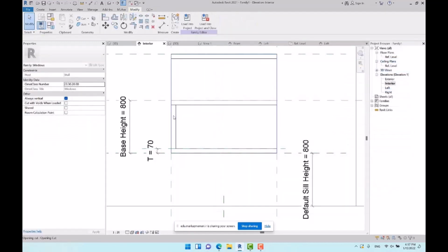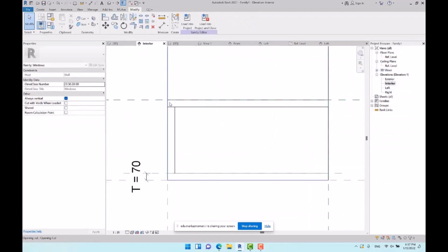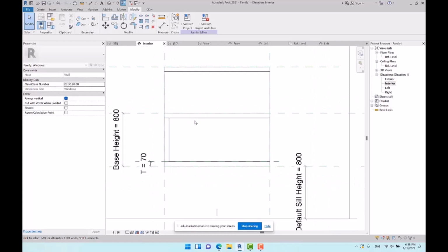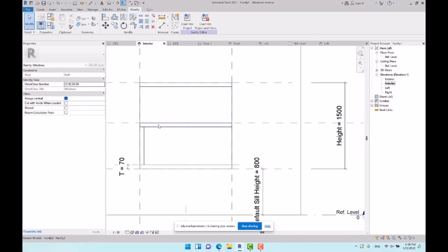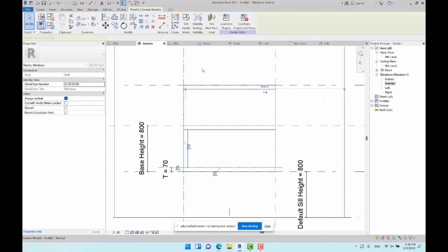Okay. Check it out. Here we can even control the joining of these two, or the order that the profiles are placed. And if you wanted to modify the order, again you should sketch two reference planes and then define a formula for the horizontal profiles. Then you have to subtract the value of thickness from width.